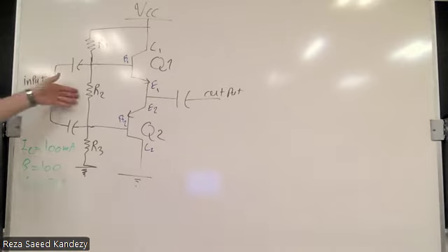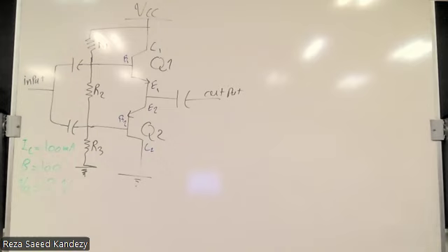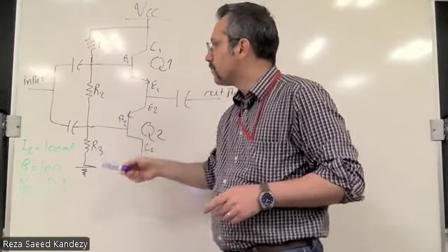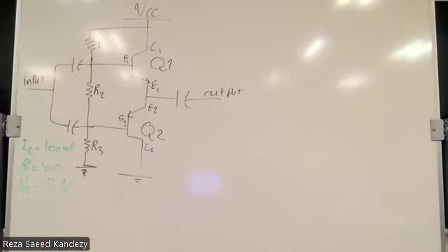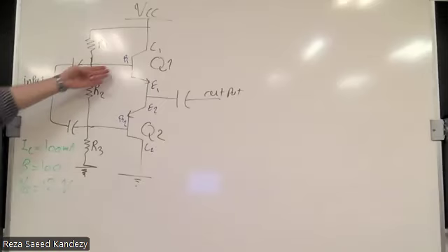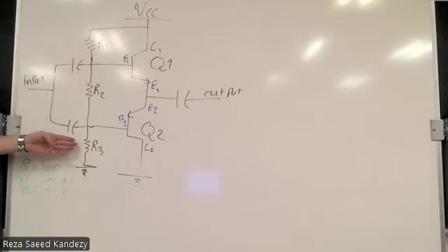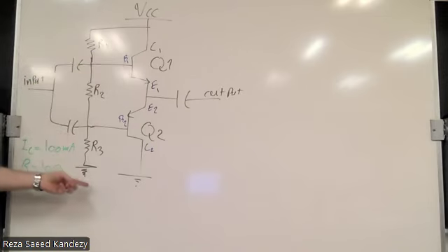Now, how do we do that? Here, we have a voltage division circuit, which we are using for the biasing. It includes three resistors, R1, R2, and R3. R2 is the resistor that connects the two bases to each other. Okay, so it's between base 1 and base 2. And R1 and R3 connect respectively base 1 to the VCC and base 2 to the ground. Are we good so far?